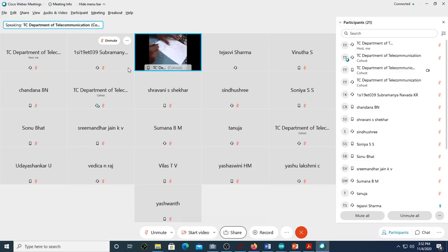If this switch is in normal condition, that is, if it is not pushed, what is the SW1 voltage? Voltage 0, sir, because it's grounded and it's an open circuit. Perfect, so it will be 0 when it is open. If I push it, then 5 volts, because it's connected to 5 volt. Even though the resistor is there, whatever current flows, the entire voltage will drop there. You will get 5 volts. Meaning if it is open, it is 0 volt. If it is closed, it is 5 volts.